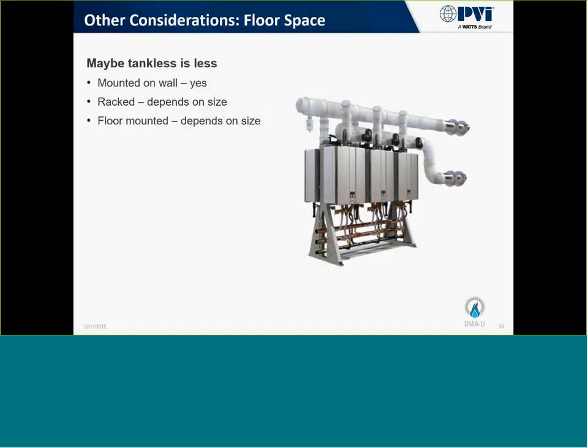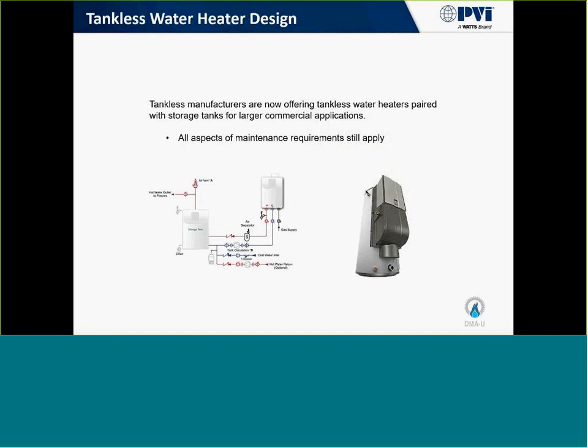You can rack them. They can prefab tankless water heaters into a skid type system. But another thing that needs to be taken into consideration is the venting and the complexity of it. So now a lot of tankless water heaters are actually coupling their tankless water heaters with storage, and that's for more commercial type applications, obviously.